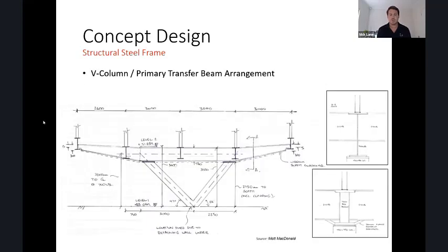These are some concepts on what the level 2 structure looked like. We had some key clearance requirements below. I don't know if Adam, you want to talk about that, but early days we were really pushing the structure design to achieve those clearances below, and that was a back and forward between the weight of the structure above, how far we had to cantilever the level 2 structure, and where we could get support in the existing structure below. We ended up with a solution that was relatively shallow, but still it was pushing the clearance requirements below.